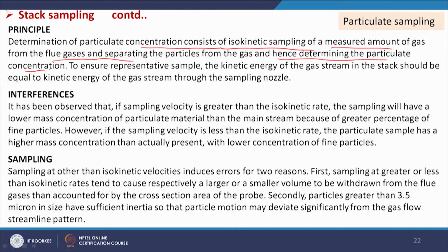To ensure a representative sample, the kinetic energy of the gas stream in the stack should be equal to the kinetic energy of the gas stream through the sampling nozzle. So, that is a very important consideration for gas sampling, and that is why different guidelines have been provided.